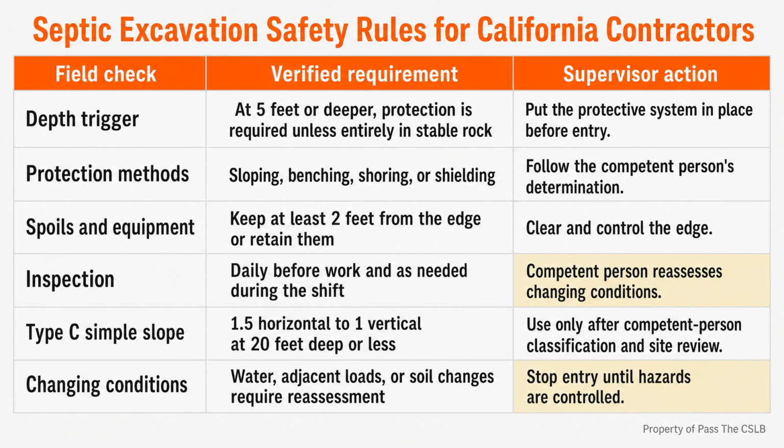A failing system can announce itself through surfacing effluent, plumbing backup, or structural failure of the tank. Surfacing effluent is identified in the statewide policy as a severe health risk requiring immediate repair or mitigation. A General B contractor who encounters that condition should secure the area, stop ordinary work from spreading the hazard, and coordinate the qualified contractor and authority.